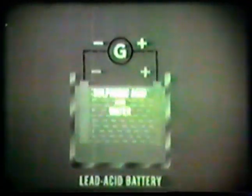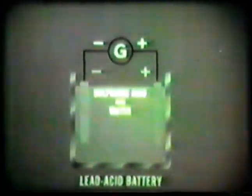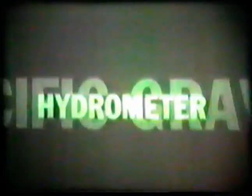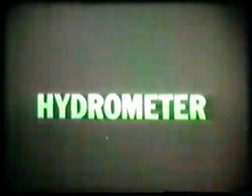The strength of the sulfuric acid electrolyte provides an accurate means of determining the state of charge of a lead acid battery. The strength or specific gravity of the electrolyte can be measured with a device called a hydrometer. With a hydrometer, you can accurately determine whether or not a lead acid battery is adequately charged.